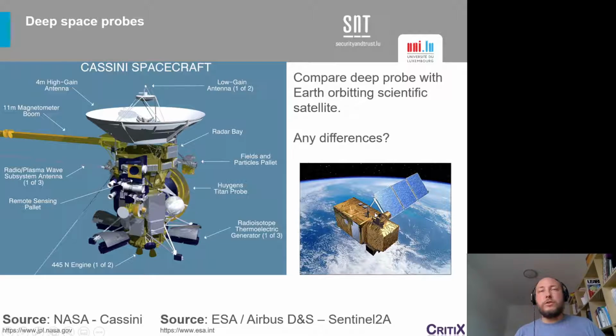Around Earth, it's pretty decent. It's 1400 watts per square meter. There's a lot of power to be used, really, and obviously closer to the sun as well. On the other hand, you can see that the communication dish is large, so it means it has huge gain and it's very direct. There's a high directivity of the antenna, which is required to be capable of establishing a communication link. And it also requires large antennas on the ground, basically.